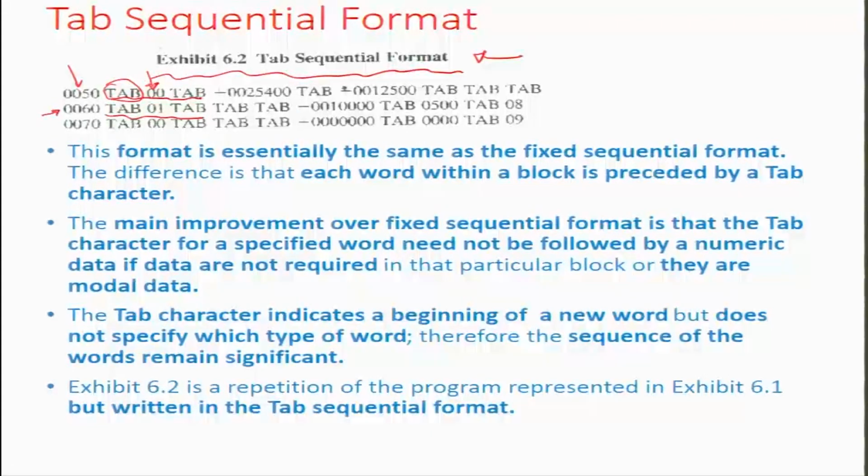Okay. So, in the next column you put the preparatory function for the machine axis to start preparing to move ahead. Again, depress the tab key on the keyboard, which takes you to the next level, that is the axis commands.